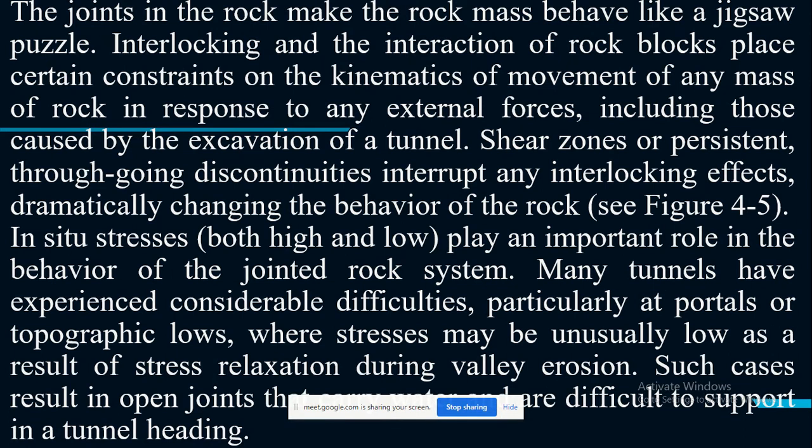So shear zones are persistent through growing discontinuities, interrupting interlocking effects, dramatically changing the behavior of rock. See figure 4.5. In situ stresses, both high and low, play an important role in the behavior of the jointed rock system.